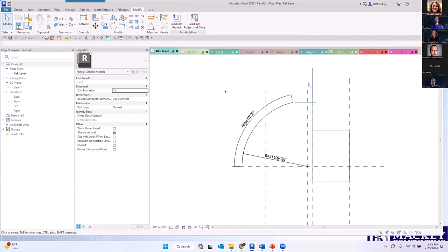And then in Revit, if you just rename that to an RFT, and I'm going to make a correction here: I tried doing this the other day in Revit 24 and 25, and they broke that. So I'm not sure if it's going to work. I've got to actually get with some of the Autodesk people. But it used to be that you could just rename that RFA to an RFT, and now you have a Revit family template. Go start a new family from that.